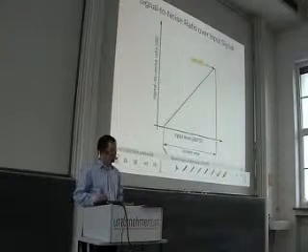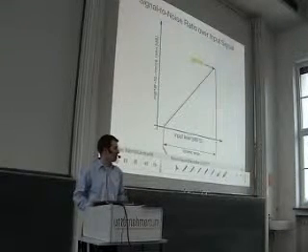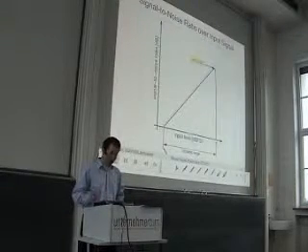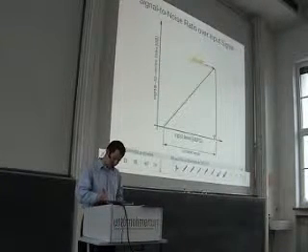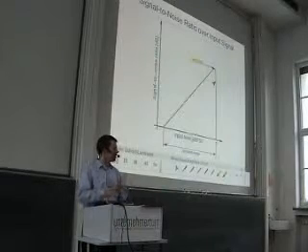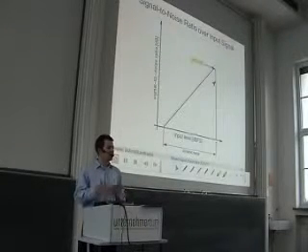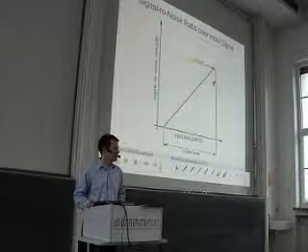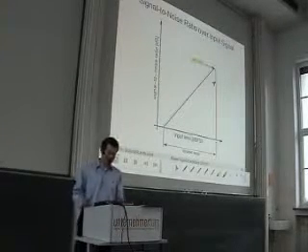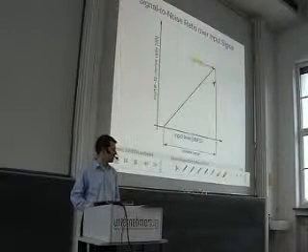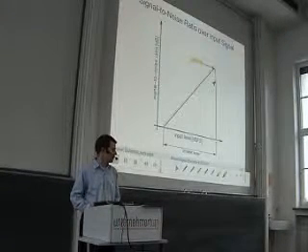Usually the dynamic range is a little bit larger than the peak SNR. Why? Because we have this effect that we drop here. Unfortunately, peak SNR and dynamic range are often mixed up. The difference is usually not so big, but a clean definition is here.